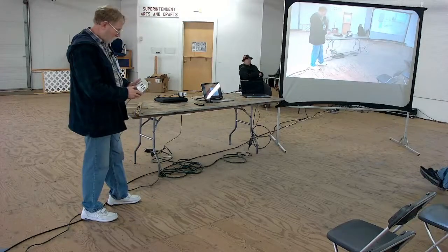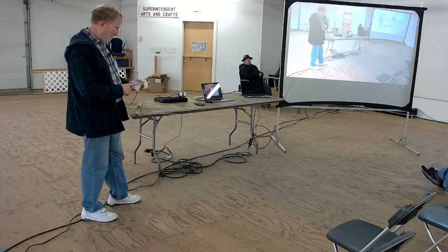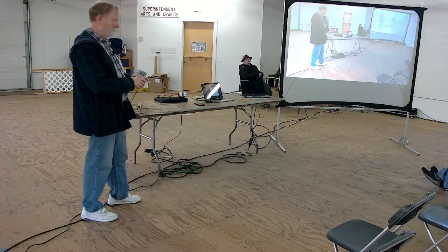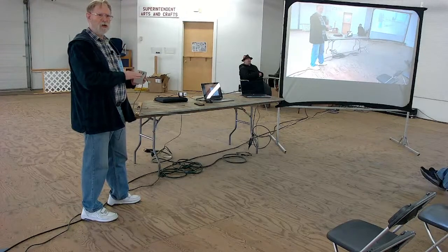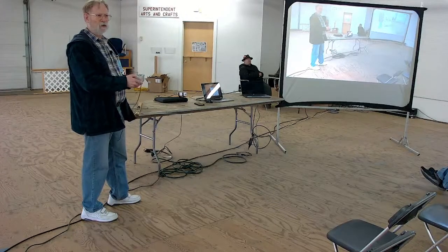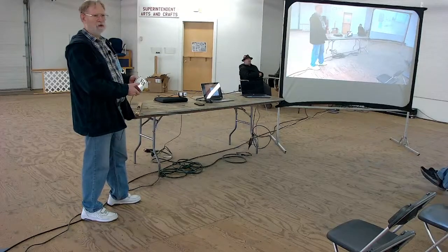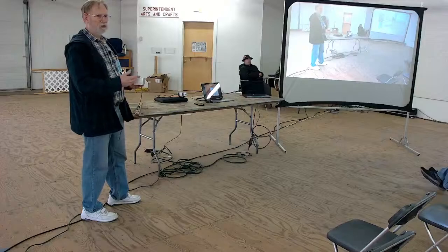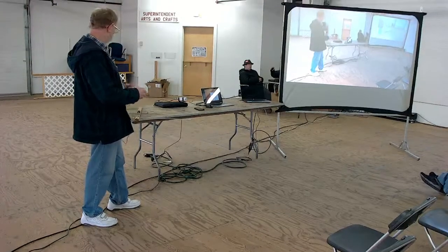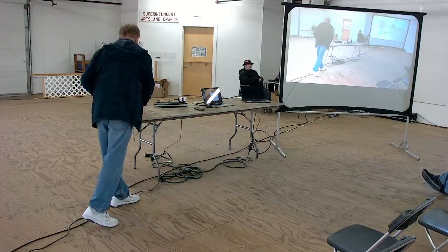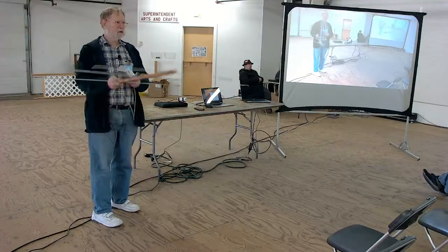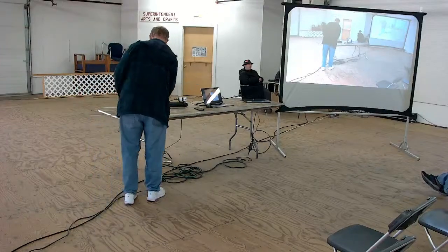So what I have here inside this box is a Radio Shack transistor radio that you used to be able to buy when Radio Shack was still around. And it has the aircraft band on it. So this radio is set up on 135 megahertz, and it's in a shielded box because I had to find a way to connect the antenna to the radio, and I wasn't able to disconnect the ferrite antenna. So I put it inside the shielded box, and that way it's only listening to what's coming from the Yagi antenna. Once you have this set up, it's real simple to just walk around and point the antenna at this phone pole or that phone pole and see which one you hear.